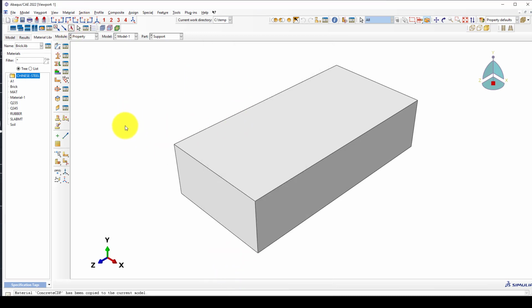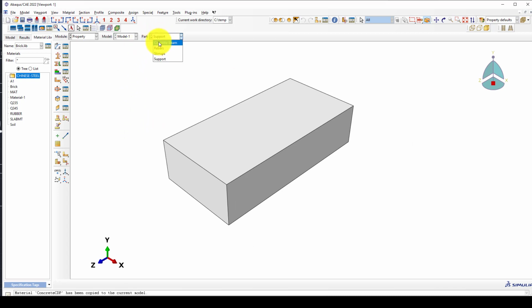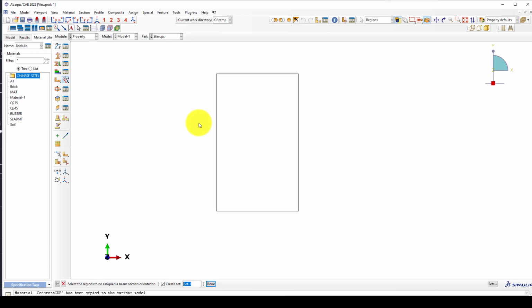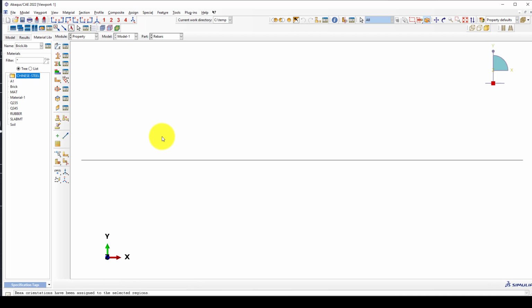The material is finished, and one thing I should say is that we need to define orientation, because this is a beam element. A beam element always needs orientation, so I can give this one, it's okay, and this is a circle, so it doesn't matter which direction you give, whether x, y, or the moment of inertia Ix or Iy, and the same for this one, assign it.